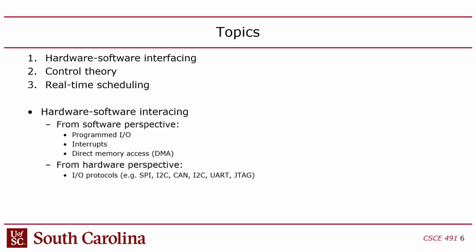And you'll find that in this class, we have a lot of them, where some of the bits within a single word are read-only and some of the bits are write-only, right? So the whole control and status register thing doesn't really make any sense anymore. It's just I/O registers. Does that make sense? Okay, so that's essentially how software talks to hardware, through the load store interface.